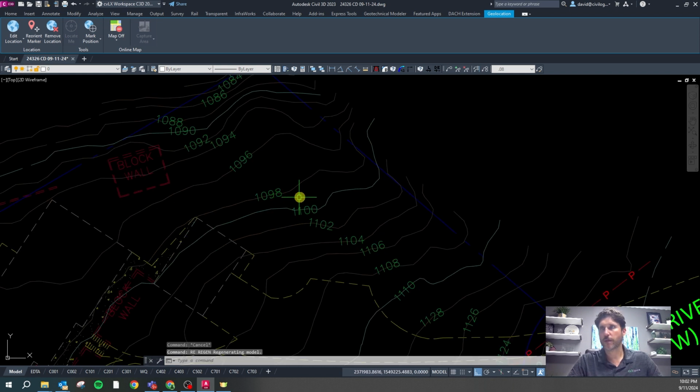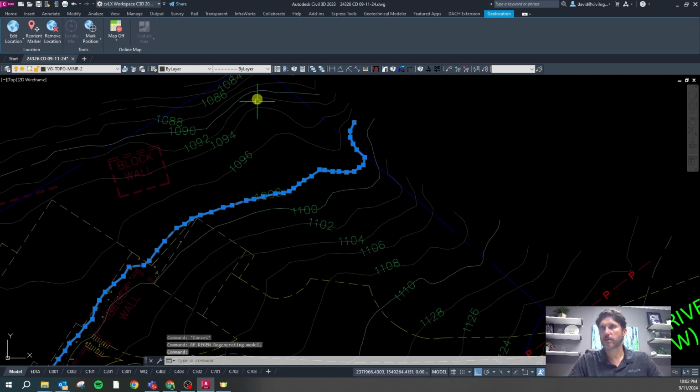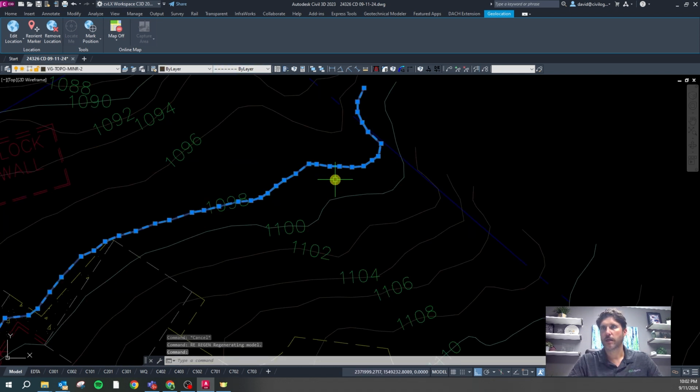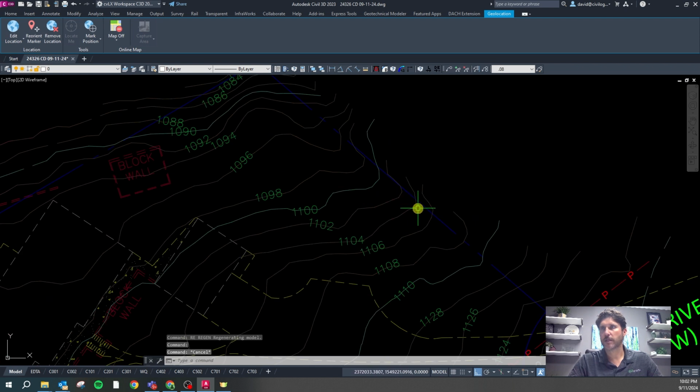Oh, one more thing. These should be dashed lines, but they just look solid. That's because every time a node happens, the line type starts over again, and it doesn't have enough length to start dashes. Here you can see these are long enough to make some dashes.